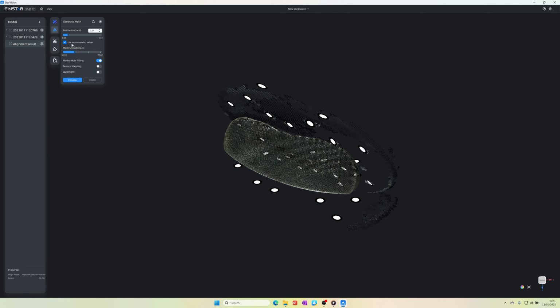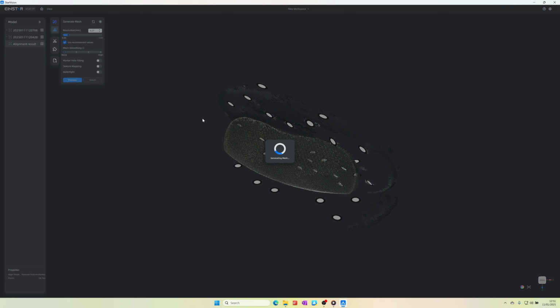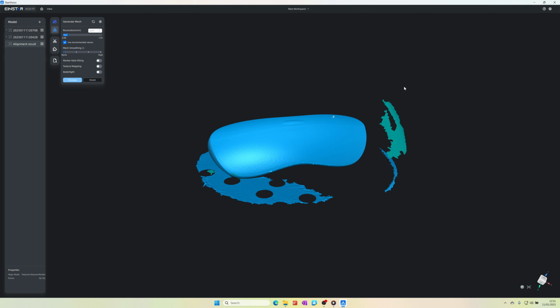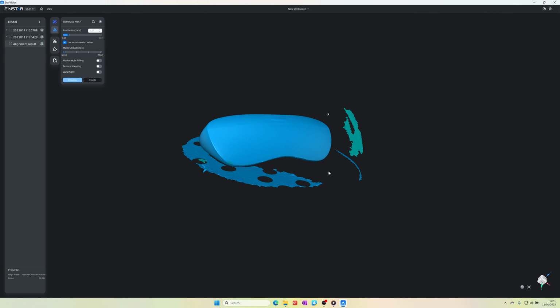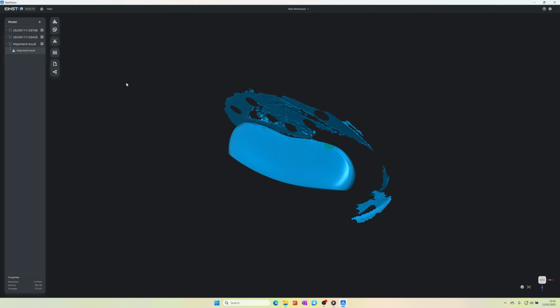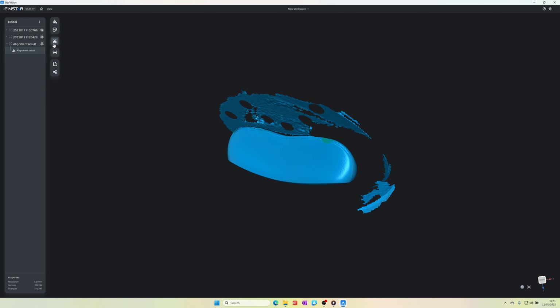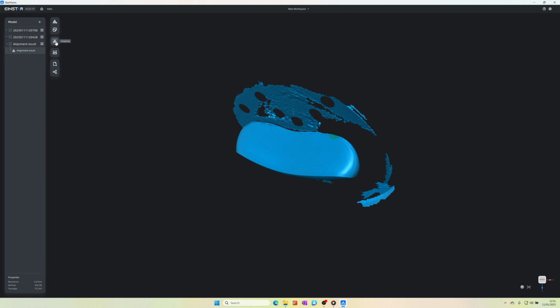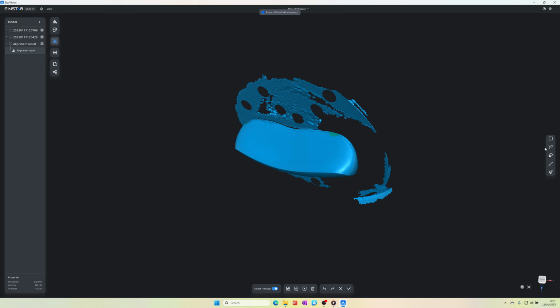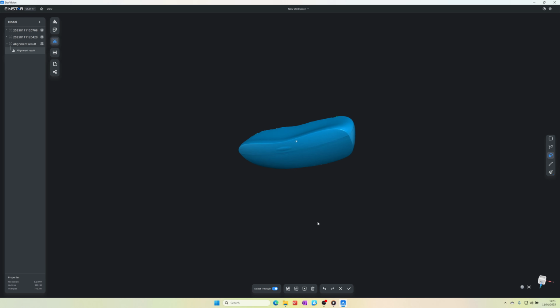Now I'll generate the mesh with recommended values. Smooth off, this off, and finally click on preview. And here's the piece almost complete. Clicking finish. Now, in this situation, I'll do a cropping. Select the piece, select the domain, invert the domain, and finally delete. And we have the final piece, which turned out quite well.